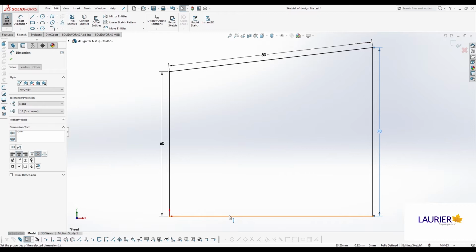First step to doing that is to look at that top line and see that it becomes kind of like a spoke on a wheel, pivoting around that point at the top of the left-hand vertical. And in doing so, because the other line on the other side of it, the one that's labeled as 70 right now, has to be attached to that line, the 80 millimeter line, depending on what angle it is, now sets the horizontal distance between the two vertical lines, which happens to also be equal to the length of the bottom line.